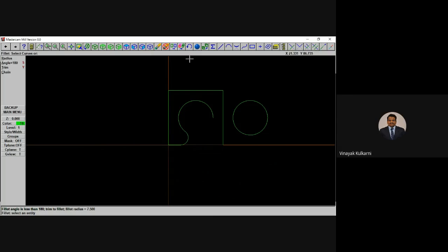This one is there. Now sometimes while selecting it happens in a different way. I'll select this and this has gone. If I undo and I select this line first and then this circle, still it is gone. Okay, so the second one is here. I want to fillet here, so it has filleted here, half. So how to retain this part, or how to have a mirror object?